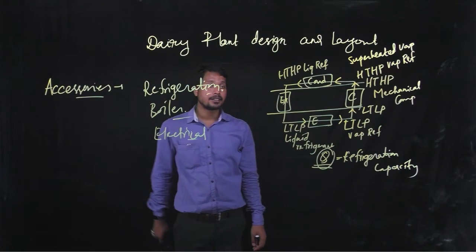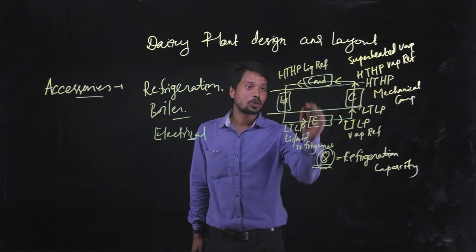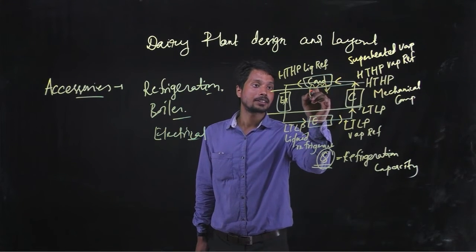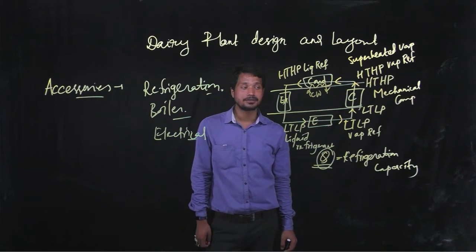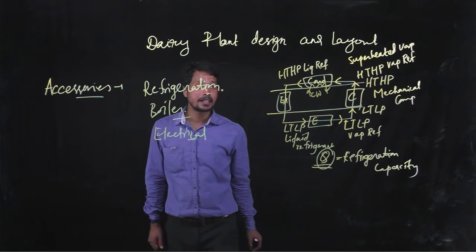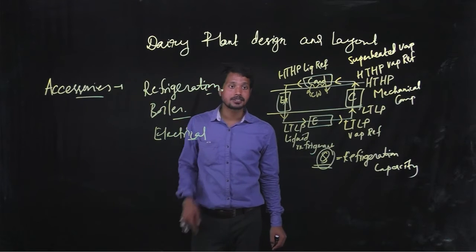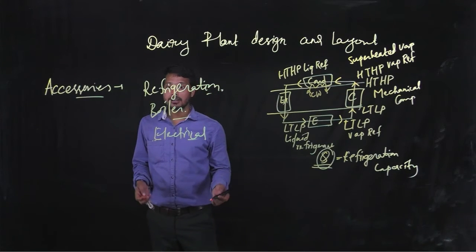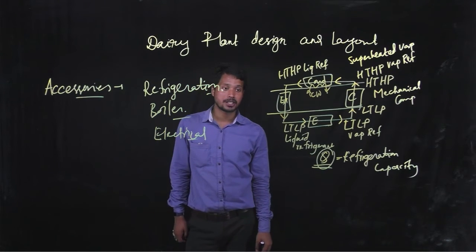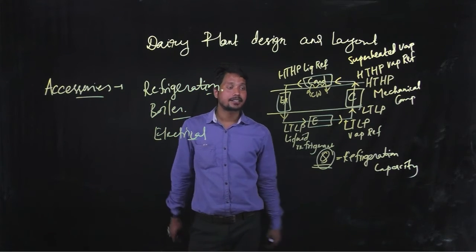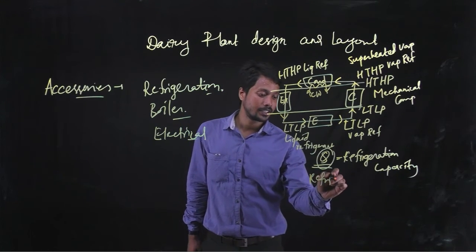Due to the phase change, here we need to supply some cold water, which changes the phase of the refrigerant from vapor to liquid. Then this high temperature high pressure liquid refrigerant comes to the expansion device, where the temperature and pressure drop again to low temperature low pressure liquid refrigerant, and like this the cycle continues. So this is called the refrigeration unit or refrigeration cycle.